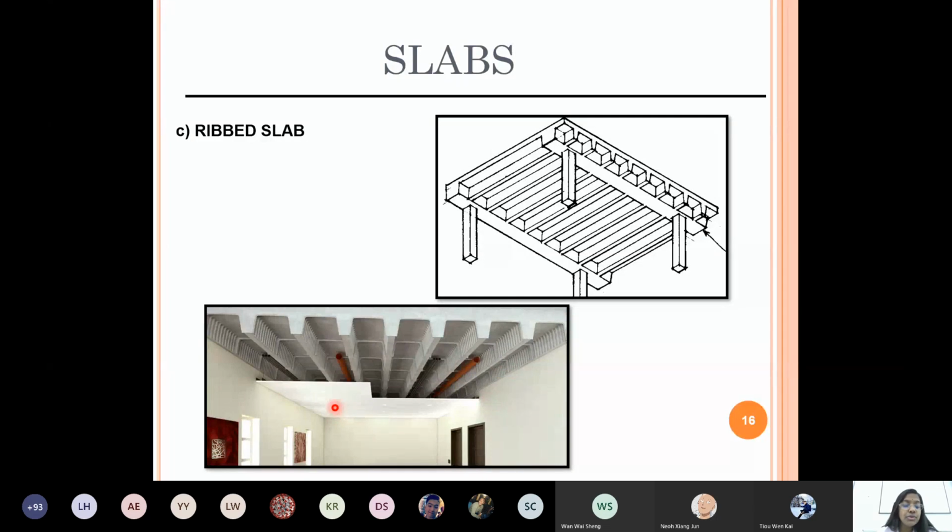They want to have a false roof. That's why they provide these types. Maybe this is a single story or double story. That's why they can go for different types like this. If you construct your own house just for a guest house or small utility purpose, not always staying there, and you want to stay only then and there, you can have an economic house design, something like this, with a thin slab and more number of beams instead of going for very high depth slabs.